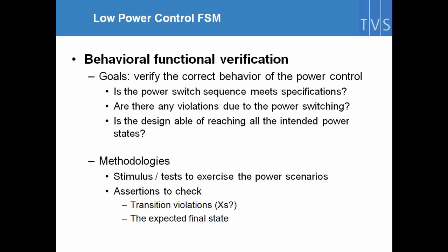We need to be sure that the state machine, depending on the operation mode, is actually going to put the design in a lower power mode. So this is mainly traditional testing, test development, exercising the registers and the functional part of your design. But then we need to check that there is no violation, and that we end up in the right power state in the end.